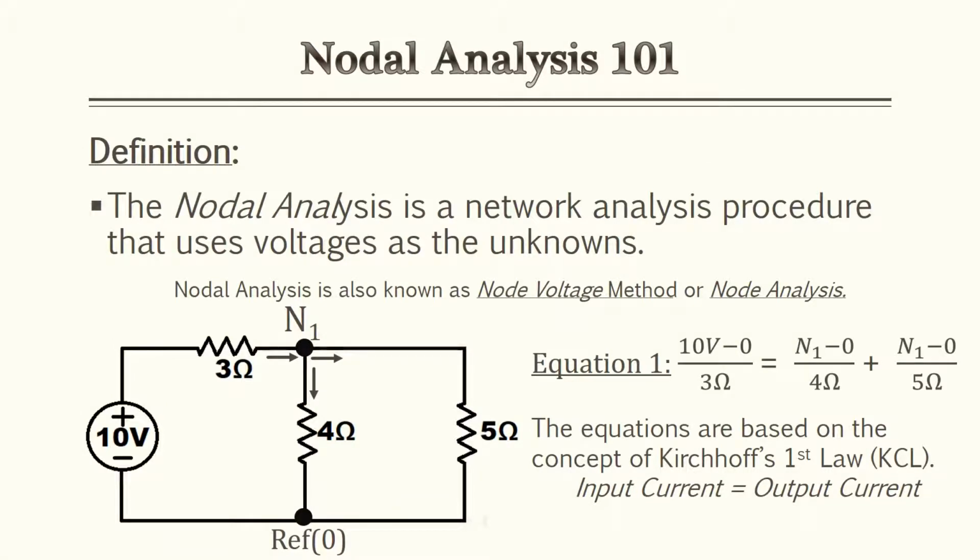For this lesson, we'll be going over nodal analysis. Nodal analysis is a network analysis procedure that uses voltages as the unknown. This will also be referred to as node voltage method or node analysis. And nodal analysis uses the equations based on the concept of Kirchhoff's first law: input current equals output current, and we'll go over that more later.